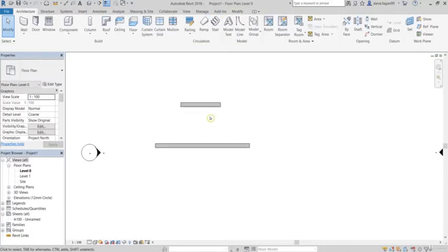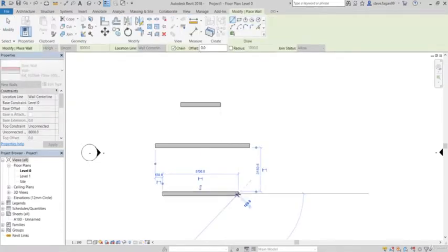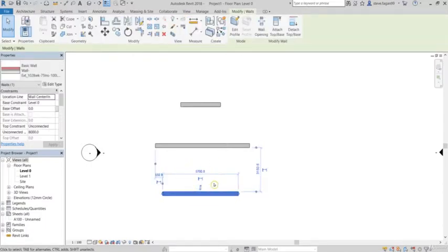The third option, which is what Revit is based around, the first thing we'll do is just place the wall, and then afterwards we'll come back and revise it. So we will place the wall, then we'll come back, select it, then using the temporary dimensions, that's where we will then revise that distance and change its length.